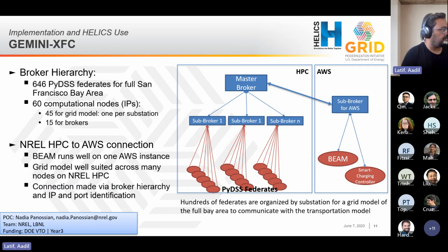All right. So when we talk about Helix, one of the main differences between Helix and other co-simulation frameworks is the hierarchy piece, right? So hierarchical framework is something that differentiates Helix from other co-simulation frameworks like FMI, for example, right? And what I mean by that is depicted well in this diagram here. Here, what we have is different simulation instances of the same simulation engine. So OpenDSS is the simulation engine here. We've got each red dot here representing an instance of that simulator, right? So each instance is running a different model altogether, a different distribution model, right?